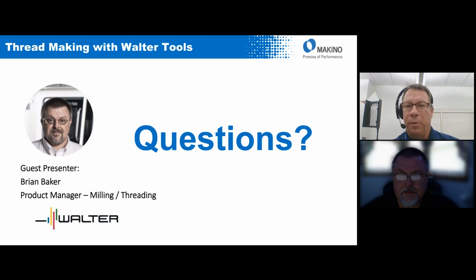I lied to you, Brian. I got one more that just popped up. Is there another advantage to thread milling multiple size threads with the same pitch? What would be your comment on that? Excellent. In shops that I personally have worked in and shops that I've done some testing in, we've had parts like that. They were doing some M10 by 1 threads, and then on a port, they had an M30 by 1. Well, that by 1 is the same pitch. It's a 1 millimeter pitch. So yes, you can use that same thread mill to do any 1 millimeter pitch threads that are on that part. It's very handy, and that's a great idea. Or a great comment, yes.